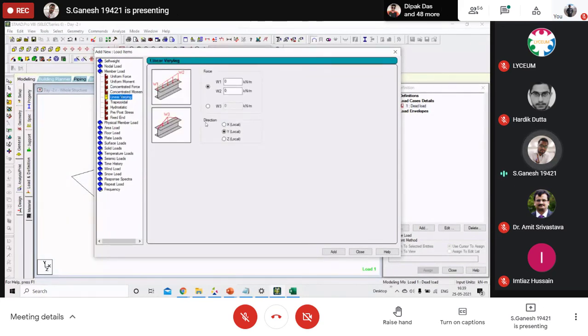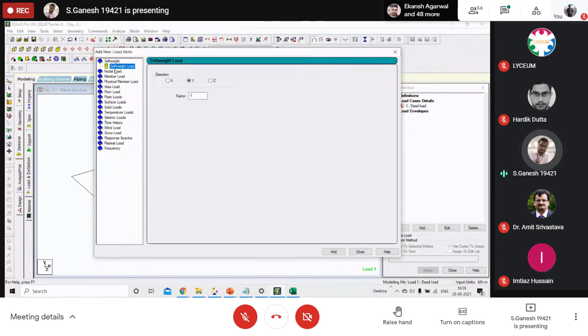So this can be used over there. The most important thing, the very first step, is self-weight. Whatever structure you create has a self-weight against gravity, so that is always in the Y direction unless you work on dynamic loading. For static condition, we use Y. We are using the static condition today, so it's -1 only. Right.